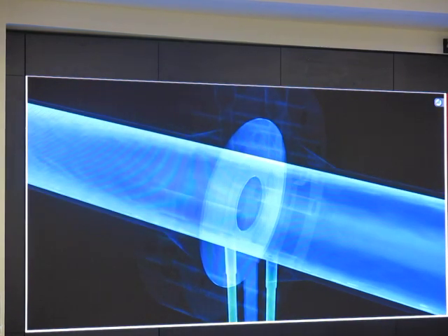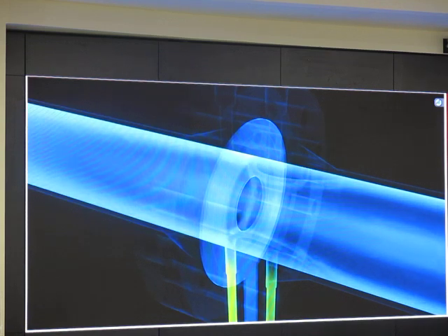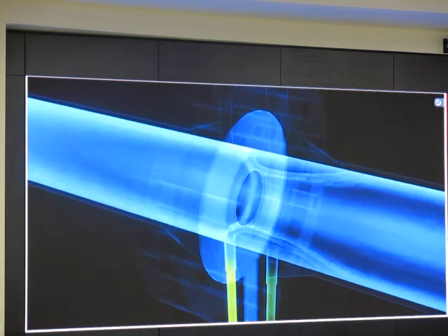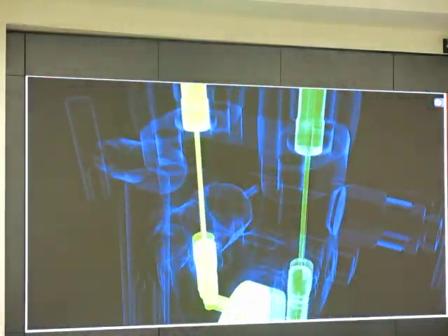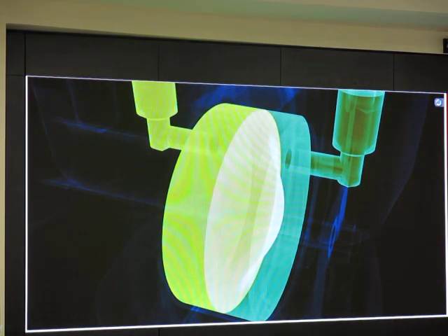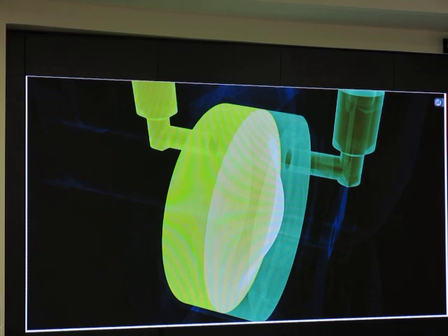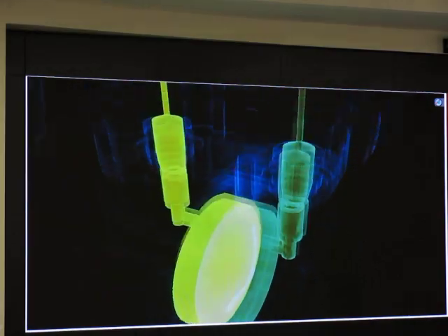If the fluid is not flowing, the pressure before and after the orifice plate is essentially identical. As soon as the fluid starts to flow, its velocity around the orifice plate increases significantly because of the restriction in the cross-section. At the same time, due to the laws of fluid mechanics, the static pressure at this point decreases. Consequently, different values are detected in the pressure chambers of the sensor, a higher pressure before and a lower pressure after the orifice plate.